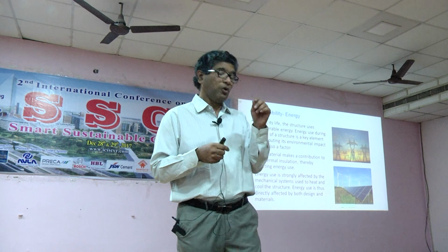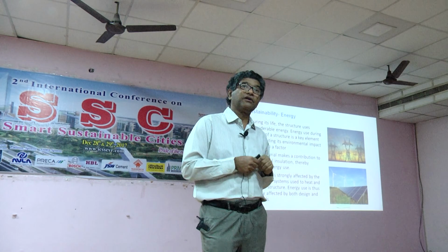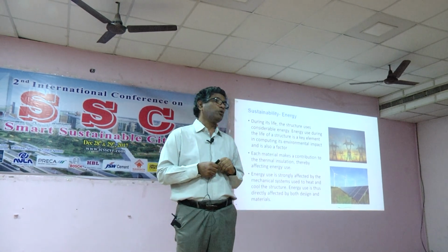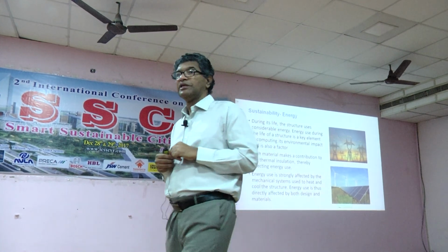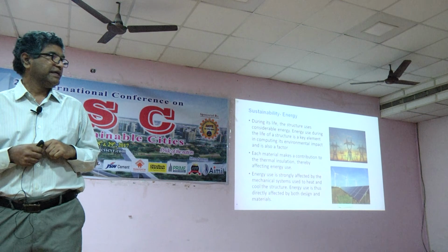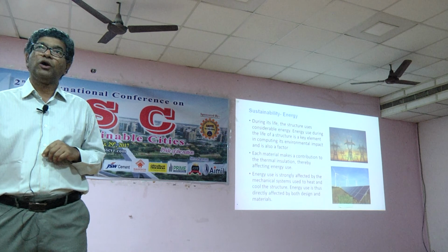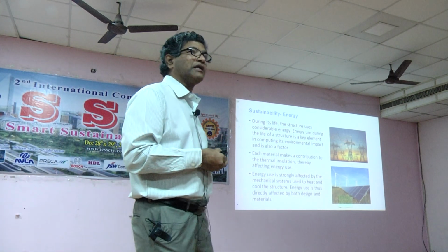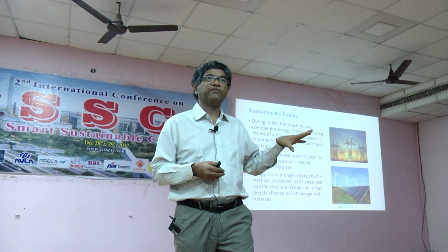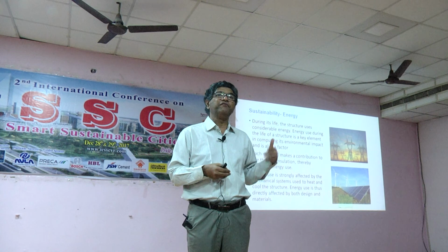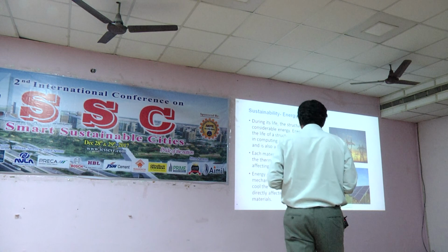But what we told the government, directly to the government official and right in front of the Chief Minister, I said, sir, let's not construct ghost houses. Whatever the housing board and other people are constructing are all ghost houses, because the quality of brick is poor, right? It develops cracks and attracts moisture, and people are leaving the houses even though you are giving them free. So let's not make the same mistake. Let us do monolithic construction with concrete walls. People will stay forever and generations will live in those buildings. Those building photos I will be showing to you.